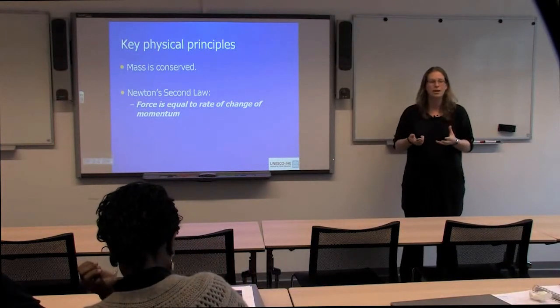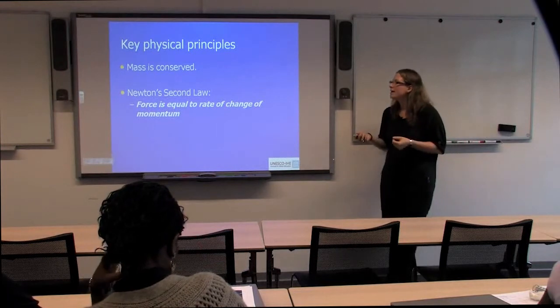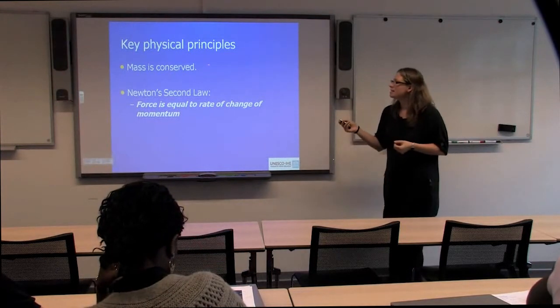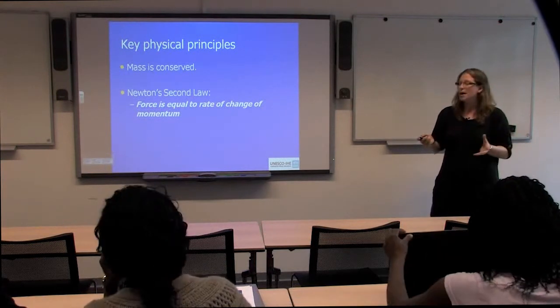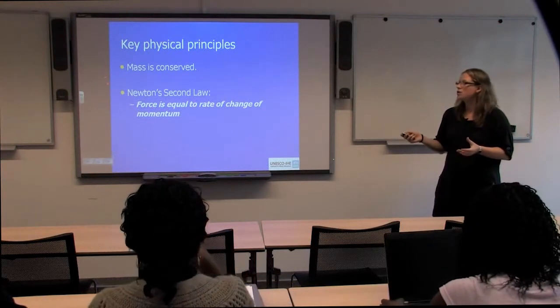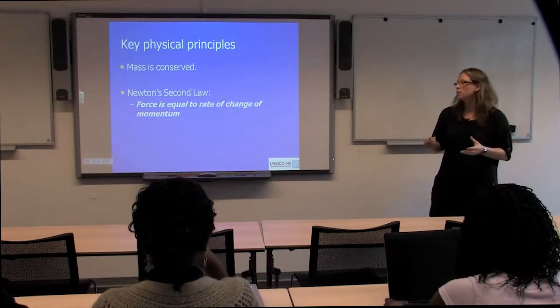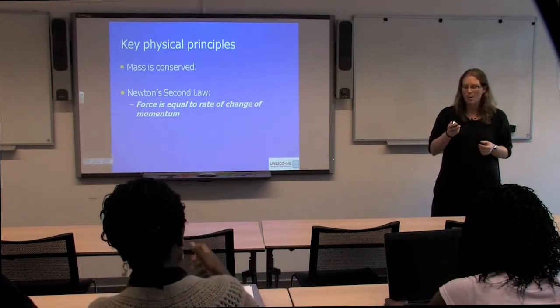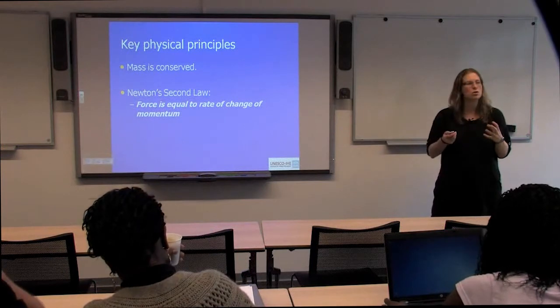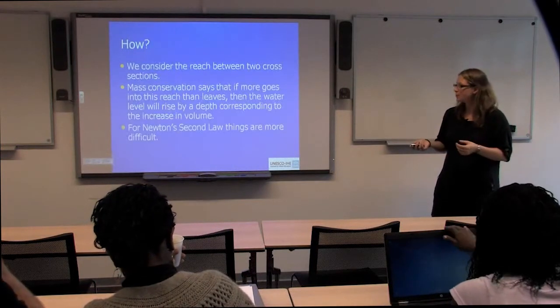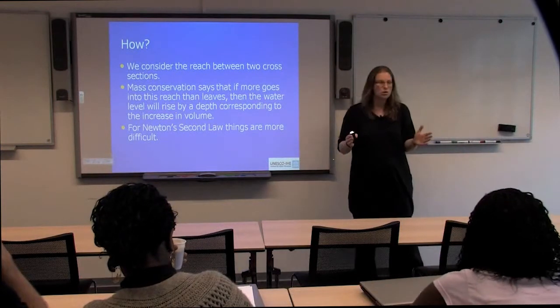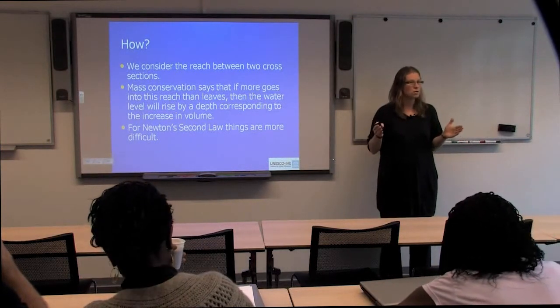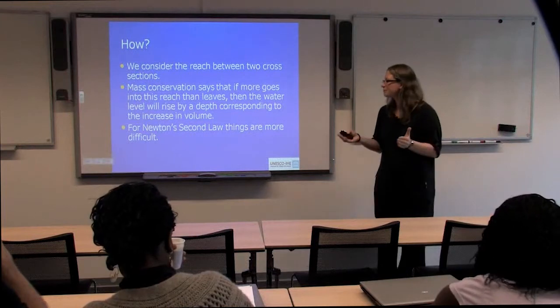The theory that we use is, first of all, that mass is conserved, which is quite a simple one to think about, and also Newton's second law, where force is equal to the rate of change of momentum. So we use those two key physical principles, and we always do that between two cross-sections, which is why these cross-sections are very important.